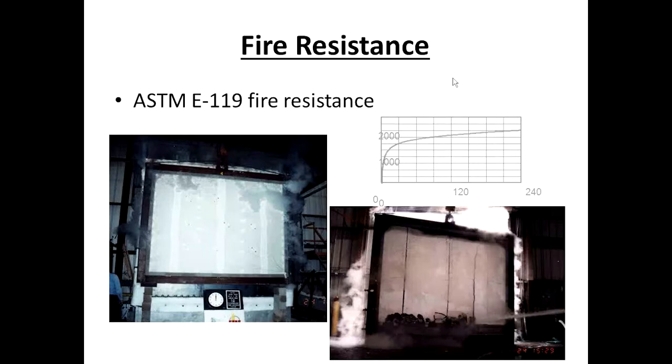And we would take those numbers and we'd plot it and get the Johnson's empirical elastic limit and all that kind of neat stuff and determine the contribution. Or we would put a ram on one side of that wall and rack it and determine the racking strength of that partition.